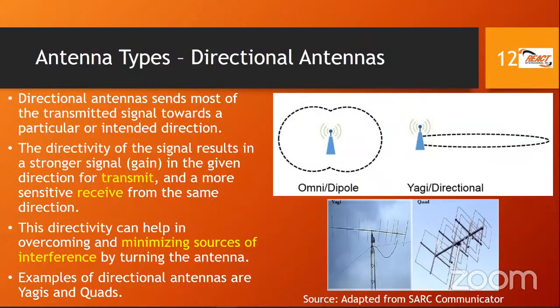So not really. The antenna is cut for a specific frequency, the one that you're going to be using regularly, or right in the middle of the band so that it's likely to be as closely resonant as possible. If there's a particular frequency that you use, I would say cut the antenna for that particular frequency. If it's going to be more general purpose, you can cut it for the middle of the band.